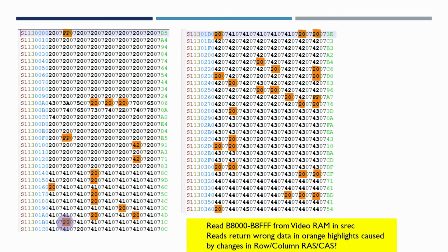And I have actually tried to ensure that all the address information is completely correct going to the video card with buffering and all sorts of other things. But you can see here that we're getting quite a lot of spaces coming out all over the place. And that really this probably indicates that some of the address lines are probably getting some of the data from another video page or from somewhere else in the memory map.